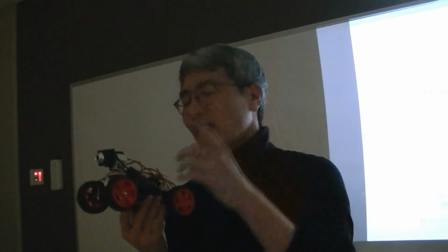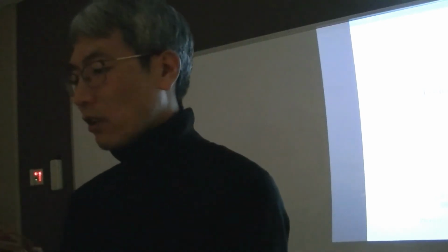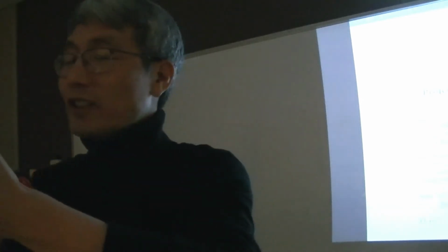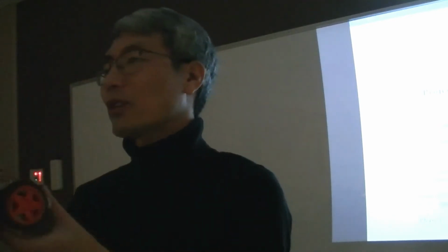Then what we're going to do in this semester is basically one thing. I already implemented the lane detection. So you can follow the lane. It's not based on data mining or any machine learning technique. It's just based on image processing. It's a very simple image processing technique to detect the lane, then follow. If the lane is tilted, then control the steering automatically. So it automatically follows the lane. The problem is it's only a straight lane.